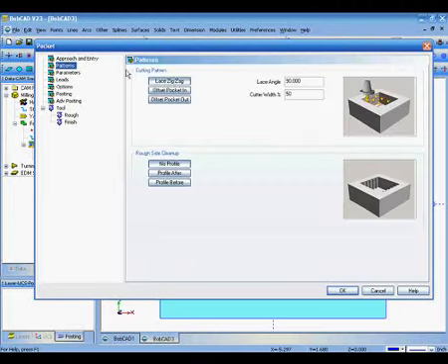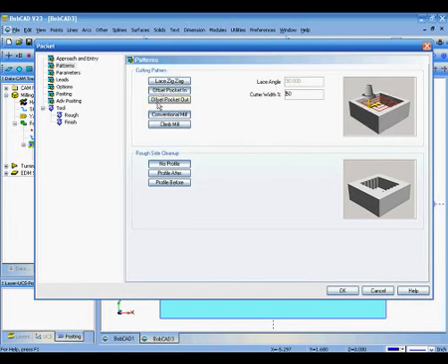We'll go to Patterns, Lay Zigzag, which will just cut back and forth with an angle based off the x-axis, or an offset pocket, in or out. Let's use offset pocket out. This will start from the center of the pocket and then work its way towards the outside. Our cutter width percentage, or step over, let's say 50% of the tool. And we'll climb mill. So we'll click on the climb mill button.